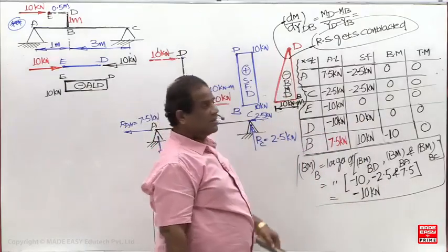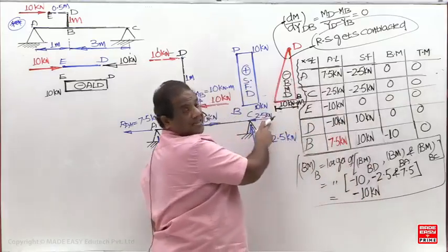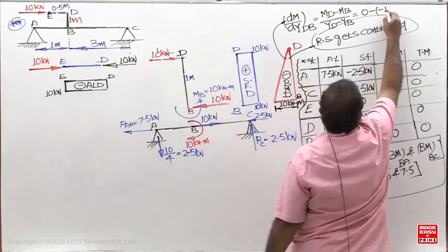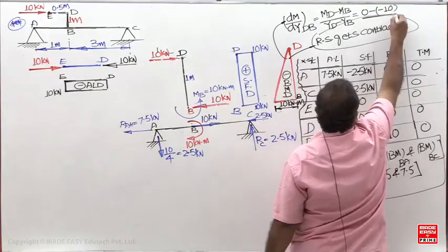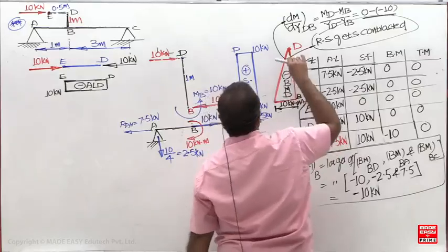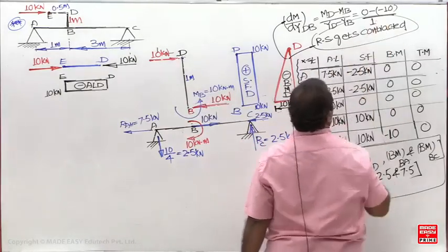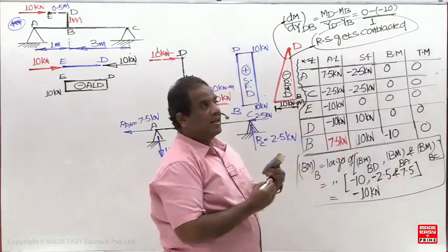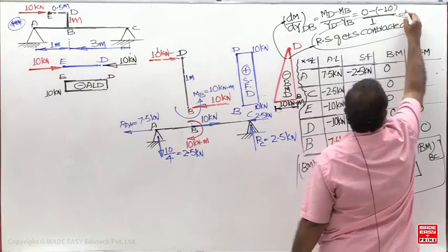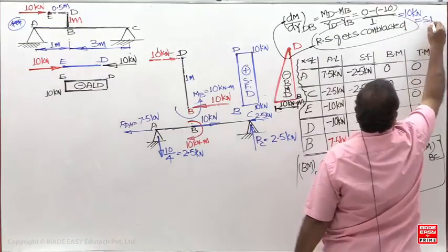Now MD is how much? MD is 0. What is MB? Minus 10. So minus of minus. And what is YD? Positive. How much is it? 1. YD minus YB is how much? 1. So what value are we getting? A plus 10. So this should be equal to the shear force of...